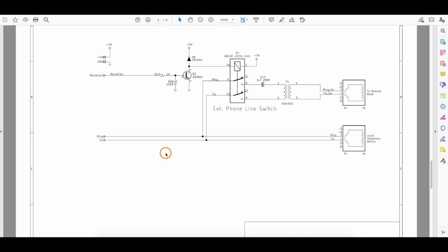And the idea is we have two duplicate setups like this entire schematic with two separate phones that you want one to call the other, and when it's time you need them to connect up so the audio can pass back and forth. So that's what this part of the circuit here does. The local phone is plugged in here and is controlled by the SLIC module. When it's time to actually let one phone talk to the other phone, all we need to do is connect the tips and the rings of two different phones together in a way that only the audio can pass between the two stations and the two phones.